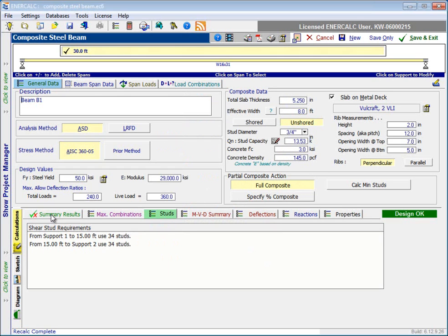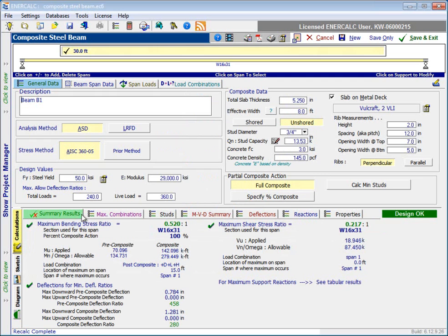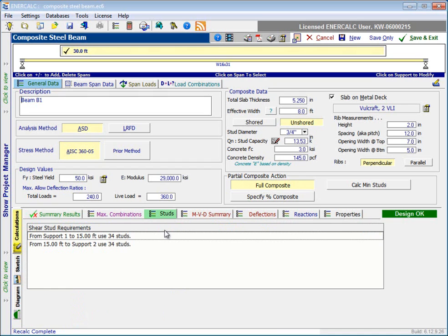And of course we would want to take a look at the summary design results here and make sure that everything still worked okay. But just keep in mind, and of course now it's a cat chasing its tail, because as the capacity goes down the number goes up and so on. But I just wanted to point out that this is the location where you would need to put some thought into what you're entering up here for a stud capacity and the assumptions that you made in that particular table. I won't follow that through in the interest of just demonstrating the module.